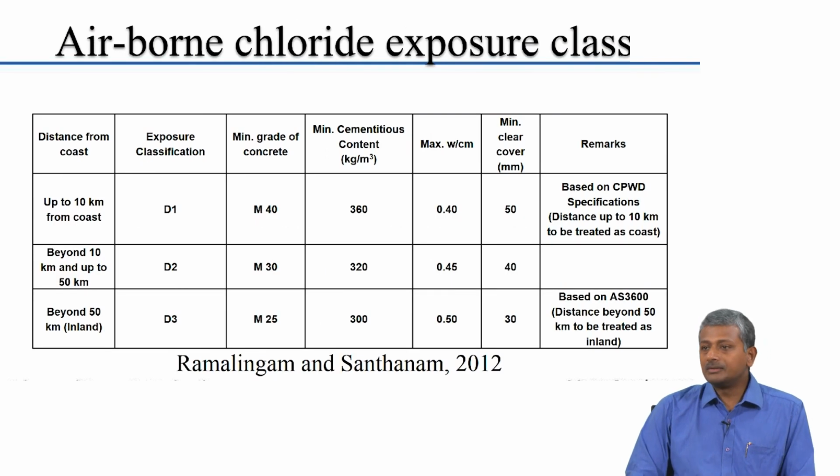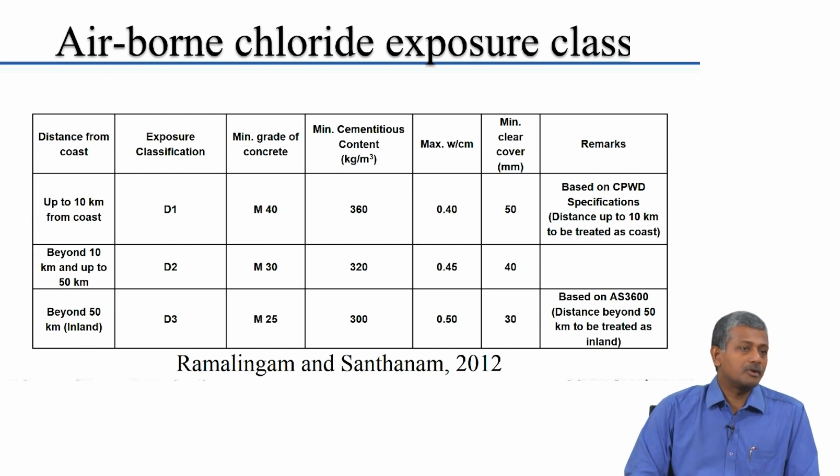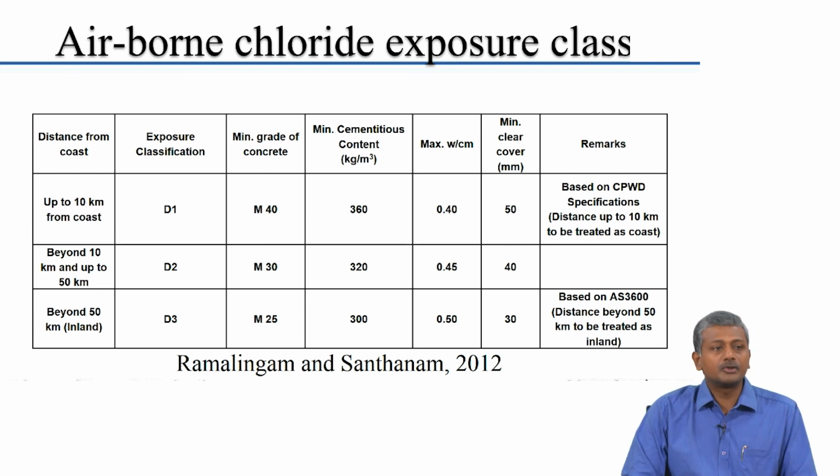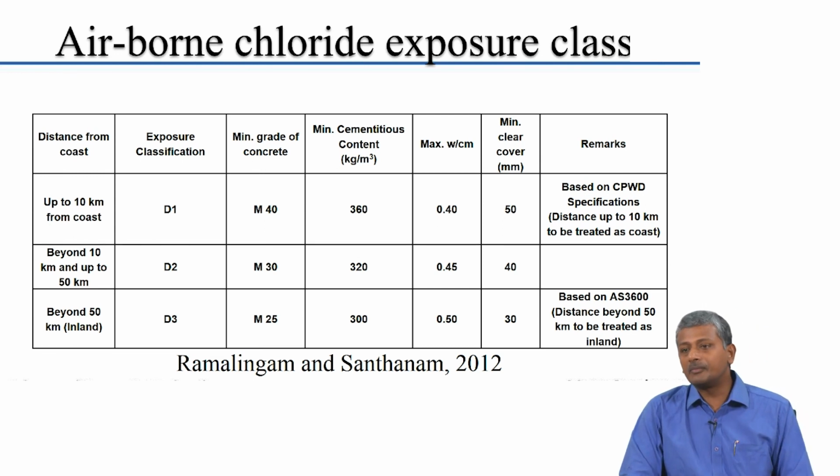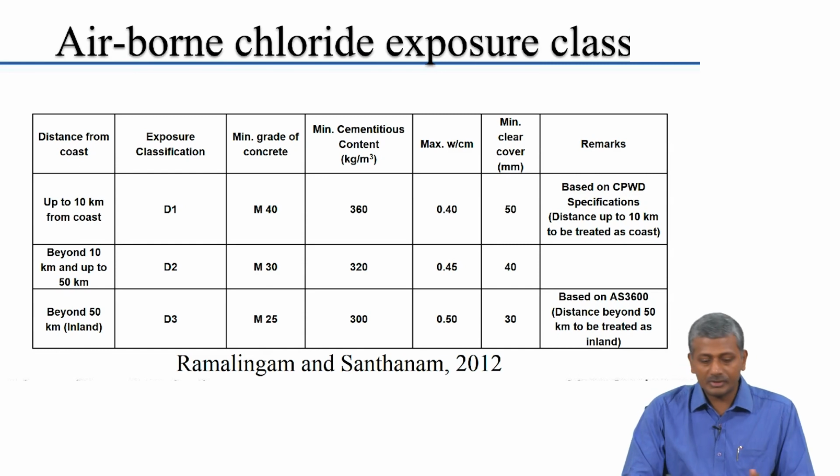Now, what we did was evaluate the durability classifications, or rather the exposure classifications given in different standards, and came up with a slight improvement on what is currently available in the IS codes. There is a lot of literature on this now, a lot of people have tried to address this issue. This is a shortcoming with our IS 456, and we wanted to add some data to show that concrete structures that were built for CPWD, the student who worked with me was actually from the CPWD.